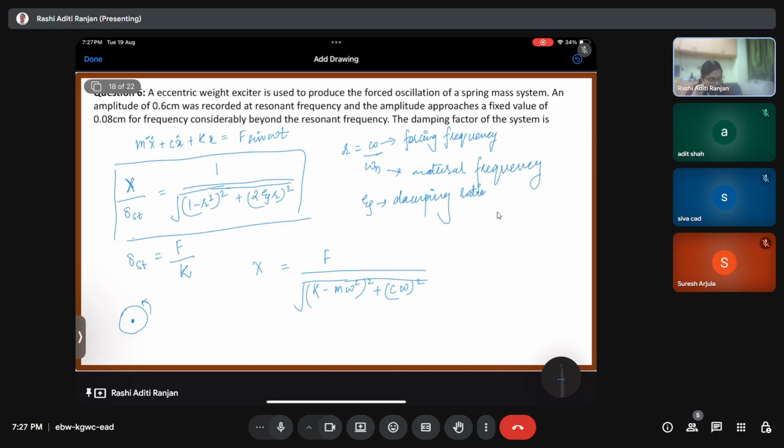If it rotates, it is not going to experience any kind of vibration, provided the mass is distributed homogeneously and evenly. If the mass is not distributed homogeneously, at some point the mass is more, at some point it is less. Because of that, it is going to have some kind of residual vibration when it is rotating. To model that, we take this disc and mount it, instead of at the center, at some eccentricity with respect to the center.